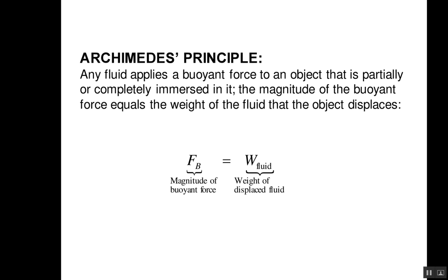Now, let's say we have a 1 meter cube box of air. Compared to water, we're going to call that negligible density. And so there is a negligible weight force acting downward on this cube of air. The buoyant force, however, is going to be the weight of the fluid displaced. Now, 1 cubic meter of water displaced is again going to be 9,800 newtons, but it's going to be pointed upwards. And so that box full of air is going to experience a buoyant force that's going to shoot it straight to the surface.